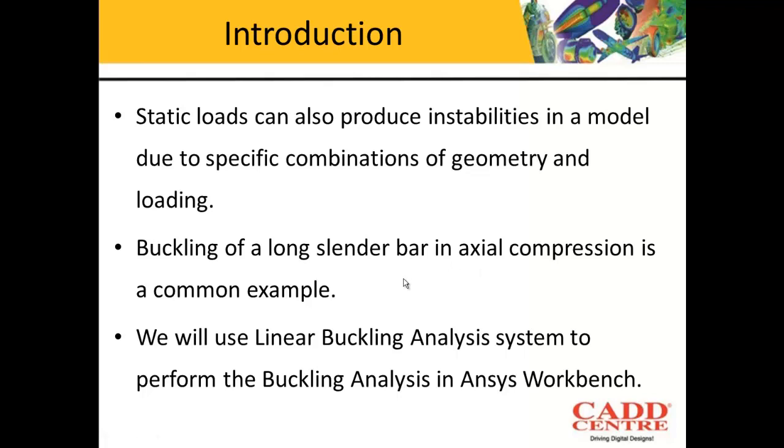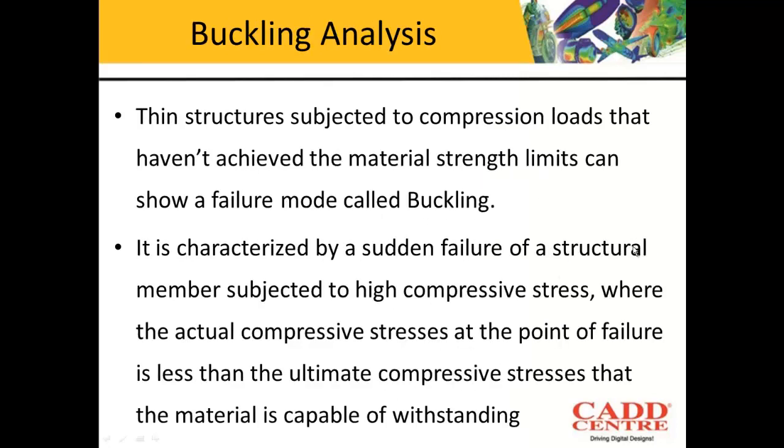In Ansys Workbench, we will be using the linear buckling analysis system to perform the buckling analysis. Now let us understand some more things about buckling analysis. Whenever there are thin structures that are subjected to compressive load, this is the same thing that we discussed in the previous slide: thin structures are nothing but slender objects. When they are subjected to compressive loads, they can buckle under some load combinations.